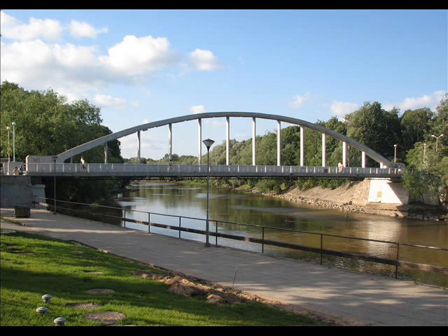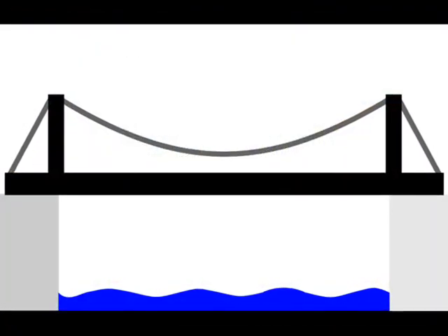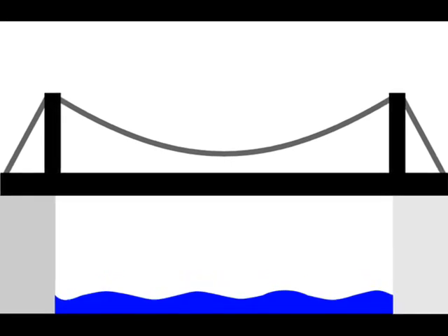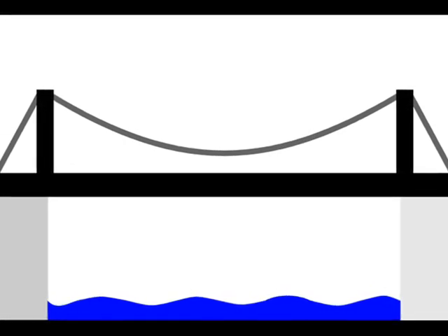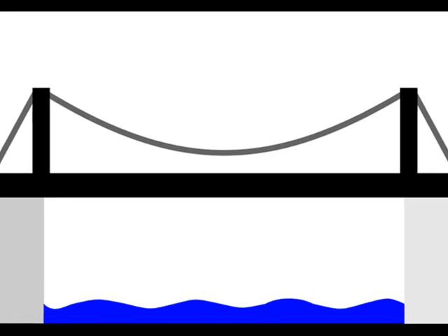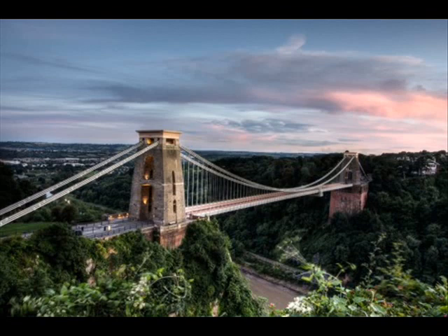Suspension bridges are suspended from cables. The earliest suspension bridges were made of ropes or vines covered with pieces of bamboo. In modern bridges, the cables hang from towers that are attached to caissons or cofferdams. The caissons or cofferdams are implanted deep into the floor of a lake or river. Subtypes include the simple suspension bridge, the stressed ribbon bridge, the underspanned suspension bridge, the suspended deck suspension bridge, and the self-anchored suspension bridge.